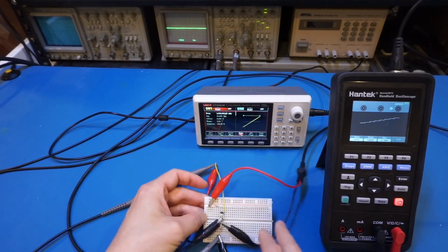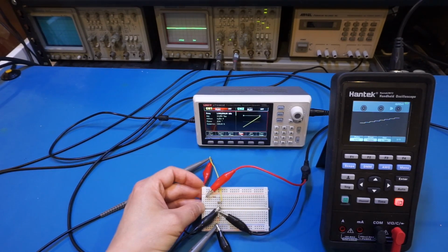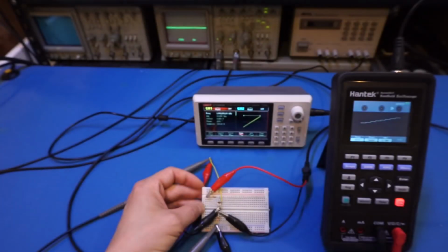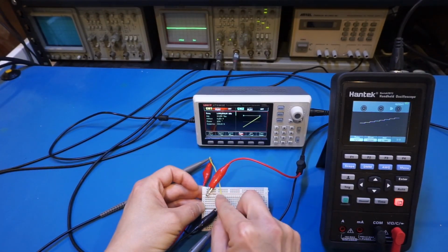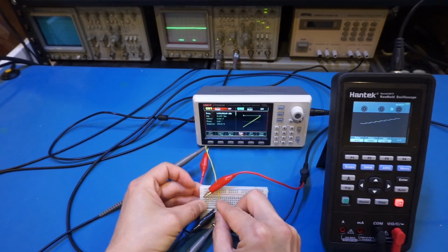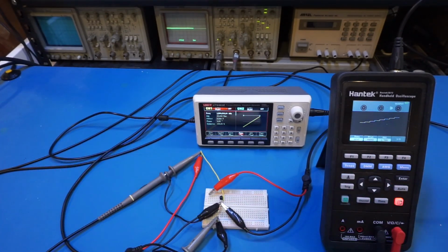Now it's a little bit hard to see, but I just want to show everything here so that you understand the overall picture. And if you do need to reference, you can always refer to the schematics I mentioned earlier. Now, the positive input goes through this base resistor, which is a 47 kilo ohm, and it goes to the base. So that completes the base driving circuitry with this staircase waveform.